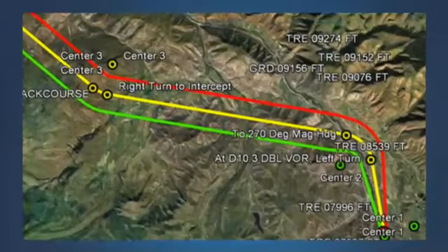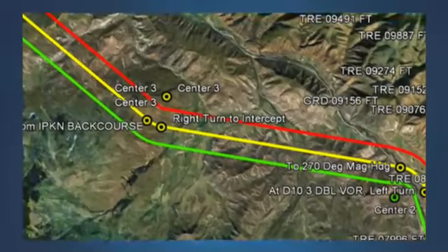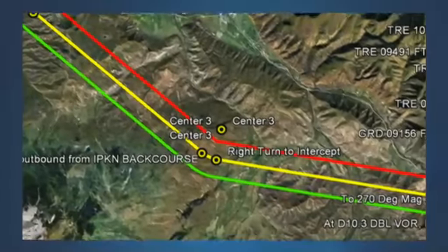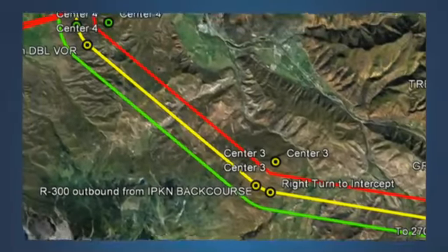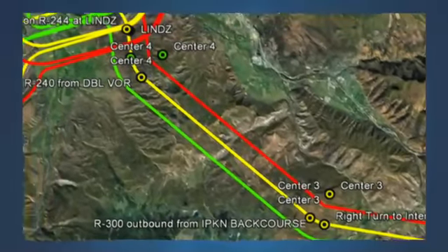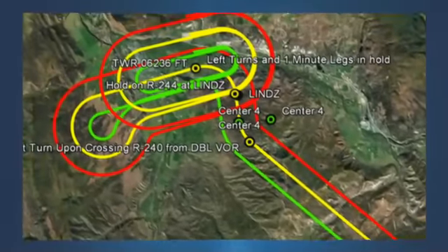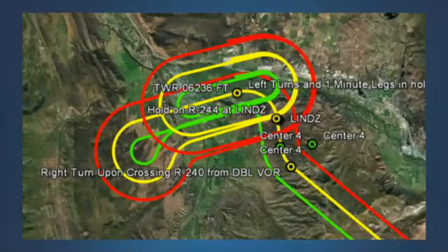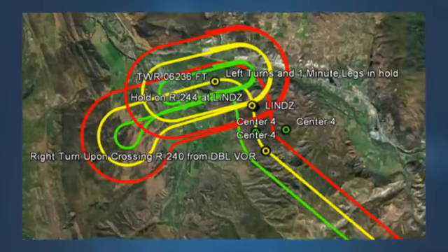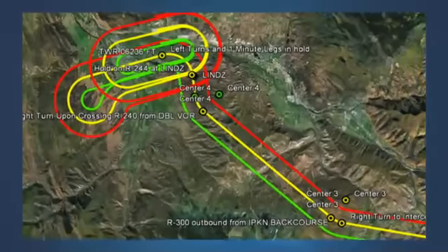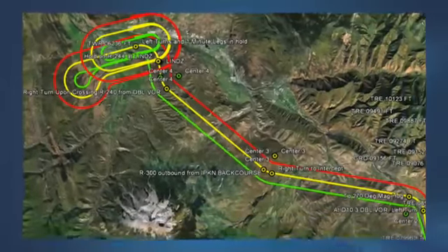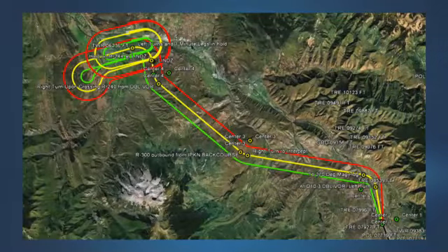On the other hand, the contingency procedures for an engine failure on takeoff are developed based on the demonstrated performance for a specific airplane type. The airplane's flight track can be accurately predicted based on the actual speed flown following an engine failure, for example V2 speed. Therefore, as we have seen, the area in which the obstacles that must be assessed for net takeoff flight path clearance is smaller than the area used for normal IFR departures.